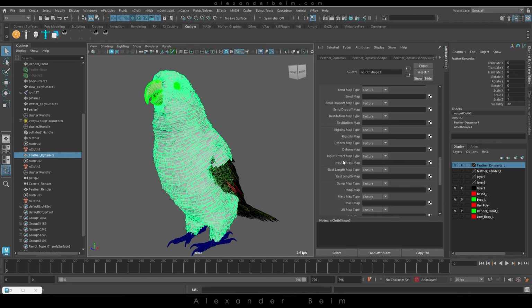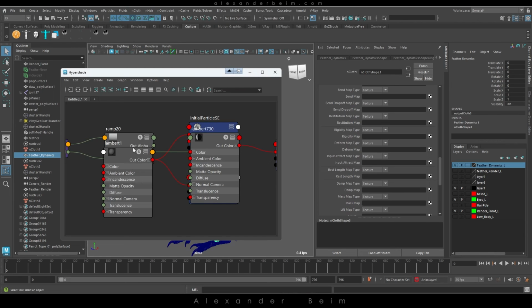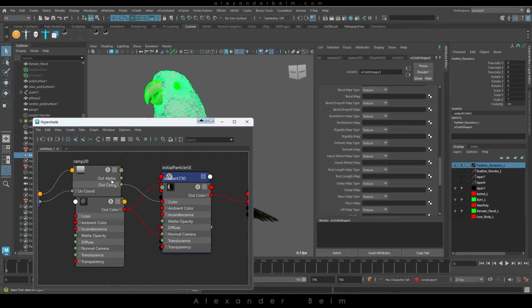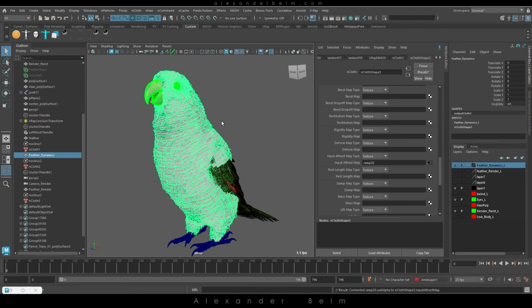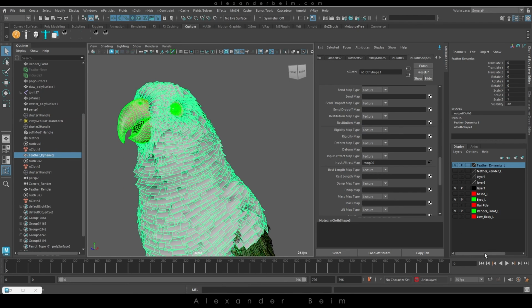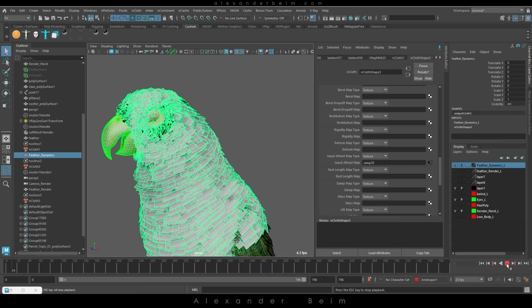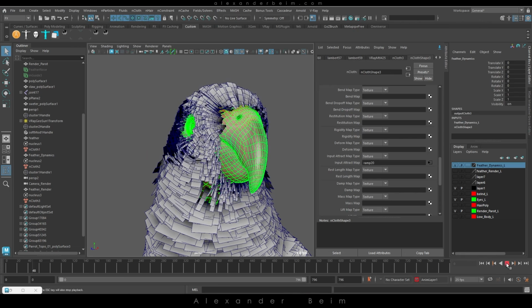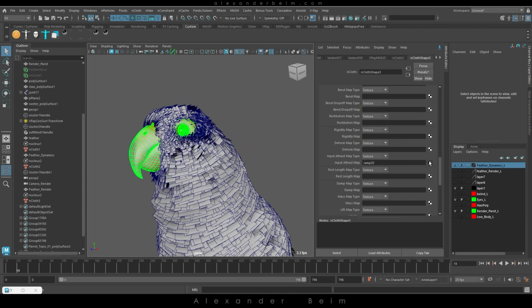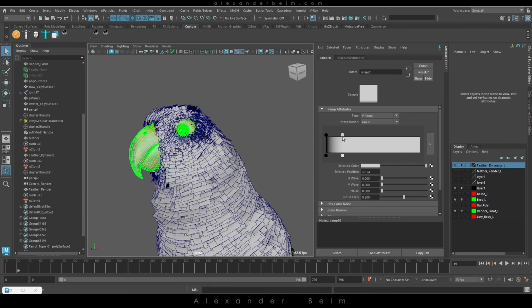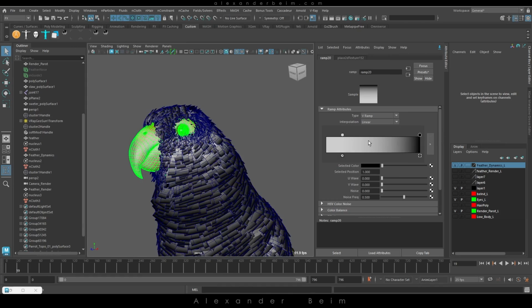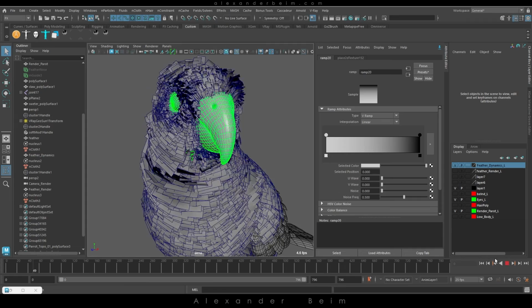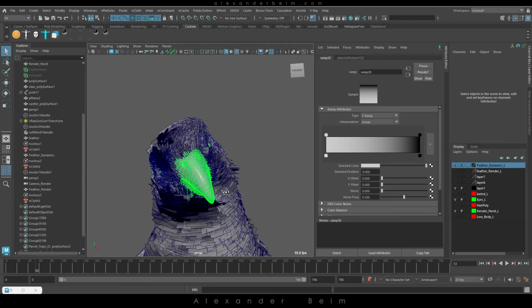Now we can go to the Dynamic Properties Maps, find the Input Mesh Attract map, and add our ramp. As you can see, now there is dynamics only on one end, but it seems to be on the wrong end. So, we swap the colors on the ramp, white to black and black to white. Now everything looks as it should, but the dynamics are too strong.